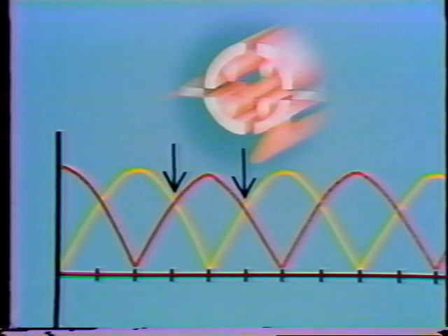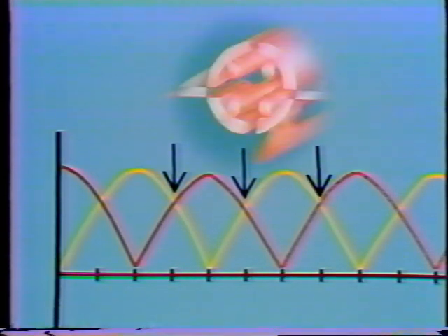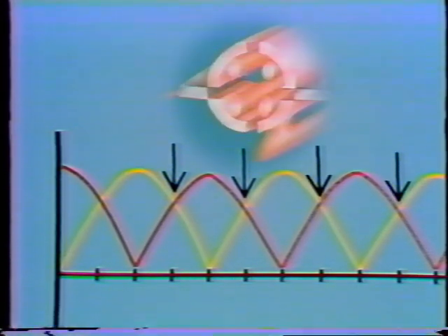This is called switching, and it occurs 4 times during each full rotation of the 2 loops. Switching always occurs when voltage in the 2 loops are equal. With equal voltages, there's no current flow during switching. Because of this switching, the generator output voltage never falls below about 70% of the peak voltage induced in either loop. 70% is better than the 50% we had with a single loop, isn't it?